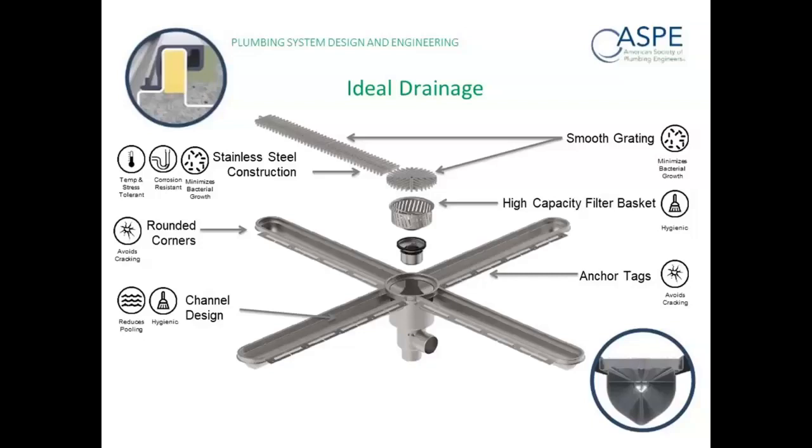And a couple other points, and Scott Garska, you can kind of accelerate this, but inside of a shoulder of a drain or a channel, typically there's a shoulder that looks like this. And the contractor is supposed to come in and fill this empty void with some sort of grout. And typically that does not happen. And if this is open in any way, water will find a way. It'll seep here and start to erode the ground underneath it.